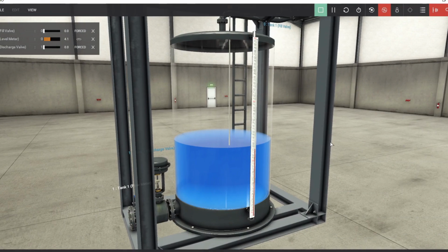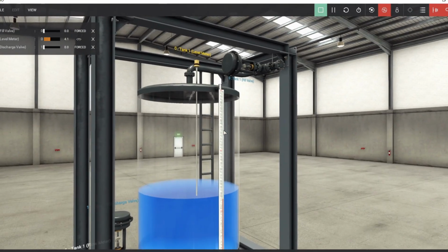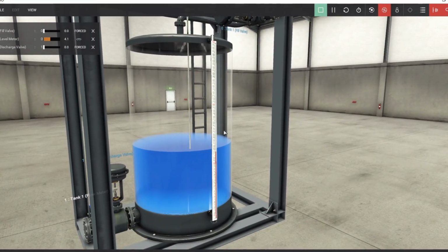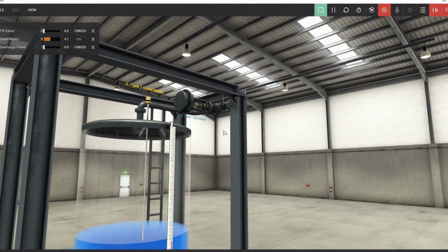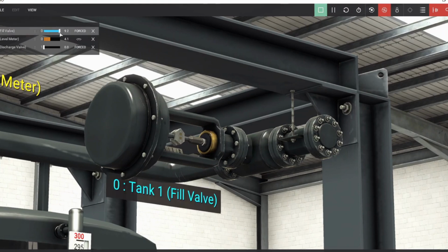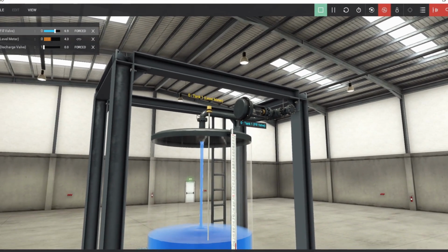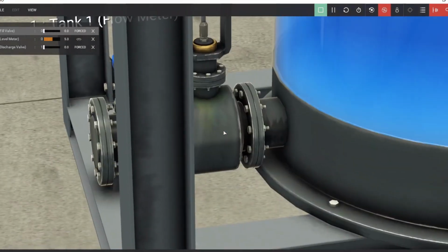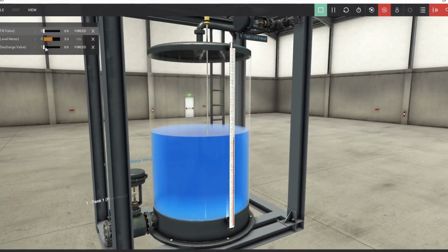Okay, so here let me briefly present the system that we will be controlling. It is a water tank that has a couple of actuators. First, it has a fill valve here that we can open, and if we open it, an inflow of water is allowed to enter, and we can close it. As I mentioned, it's controlled between 0 and 10 volts. Then we have here an outlet valve, so if we open it, then there is a discharge and the level is reduced.